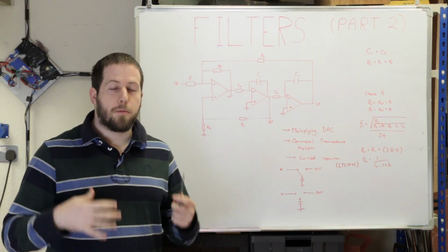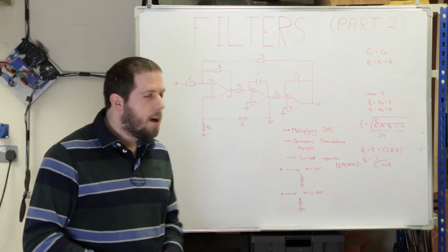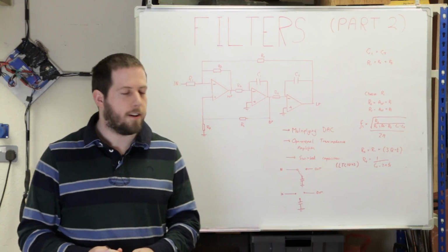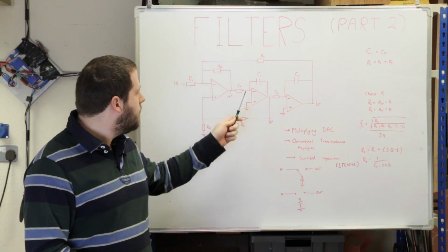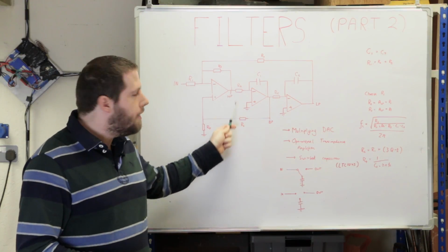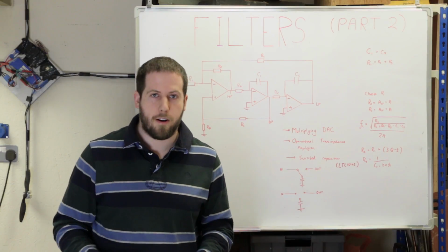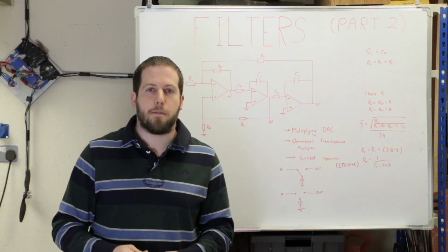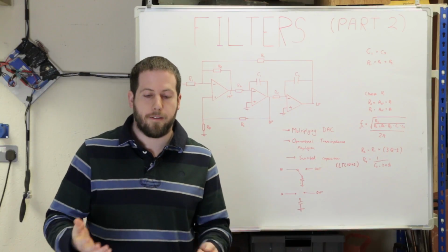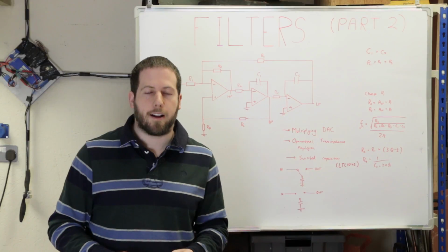So one other option, as opposed to going for a full analog multiplier, is what's called a multiplying digital to analog converter. In a similar way to the multiplier, you feed an input signal in, but the other signal is a digital signal, either via an SPI bus or via an externally available parallel bus, and that just gives it a digital number to multiply against.